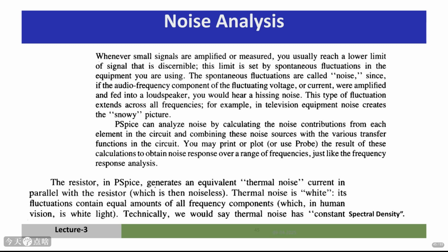In PSpice, you can perform a noise analysis. It calculates the total noise contribution from all components in the circuit and combines them. You can then plot the noise spectral density, which shows the noise power per unit bandwidth as a function of frequency. Resistors in PSpice are modeled as generating an equivalent thermal noise current in parallel with them.